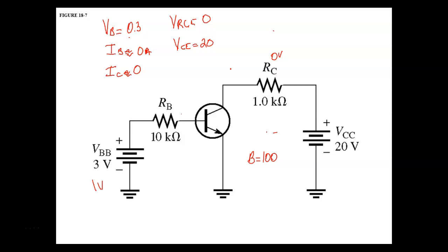We got a 3052 and 3055 out there. That sucker is a 30 amp transistor. That sucker can handle 30 amps when you saturate it, and it's in a TO3. That's going to have to be heat sinked, right? So what they try to do is put it in a package where we can mount it, but make the package as small as possible. If it can't dissipate the amount of heat, then we'll have to mount it on a heat sink, right? But that guy right there is a 2N6752. We could look that up, but a 2N3055 is a 30 amp transistor, which means if you saturate it, it could run a DC load up to 30 amps.